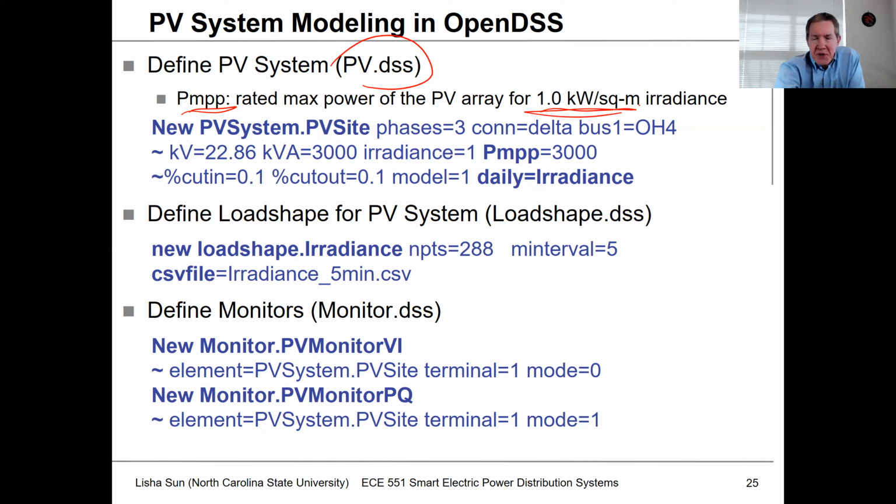And so basically what you do in this case is you're not inputting power directly. What you're inputting in this case is irradiance. Irradiance would be a number between 0 and 1. And so if you're like at 0.8, that means you're going to be 0.8 at the rating of the panel, let's say, right? And so what we do in this case is we would put in the kVA value. It's going to be 3,000. We're setting this up for the default assumption.